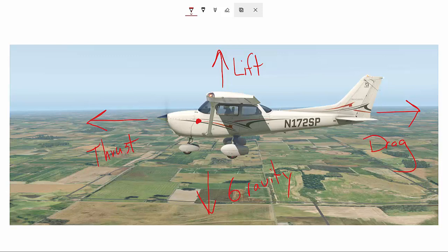On the other hand, in relation to the center of gravity, we also have the center of lift. And the center of lift is often someplace around here, very close to the spar line of the aircraft, near the front of the wing, near the leading edge of the wing. The center of lift is just like the center of gravity. It's a mathematical point where if we added up all of the forces of lift acting on the wing, mathematically, where are they concentrated the most? In other words, where is the average place where lift is acting the most on the wing? And it's a mathematical point.